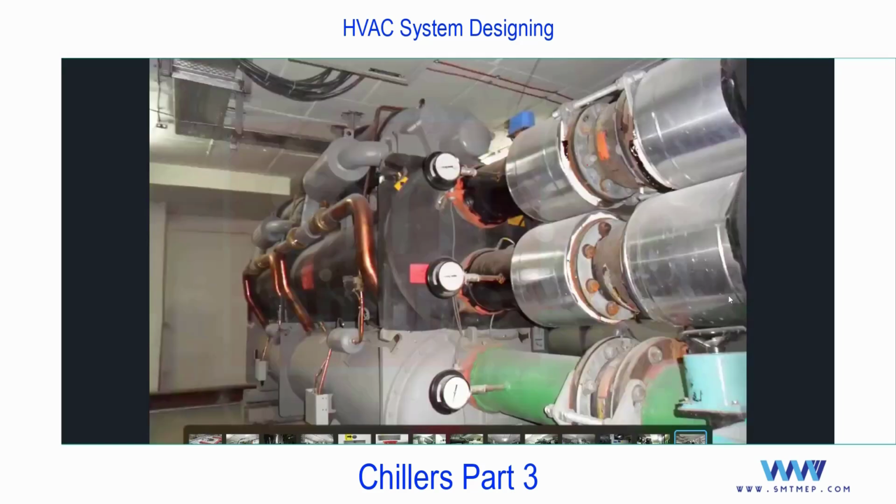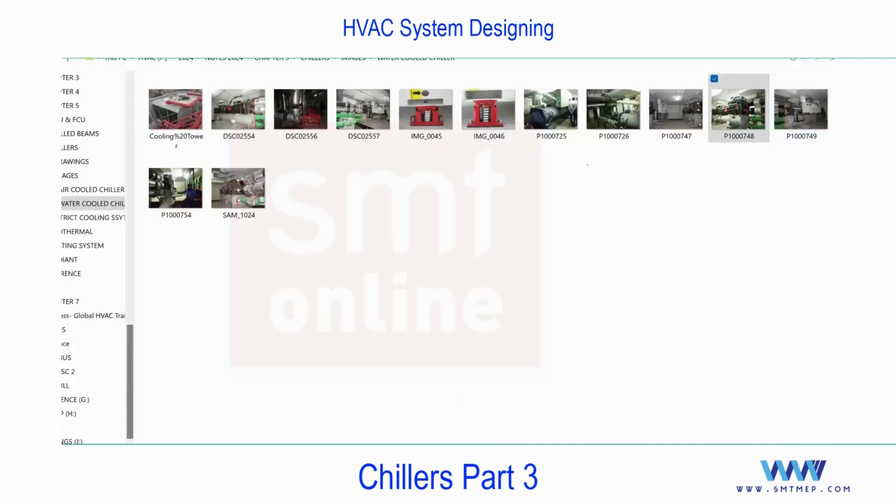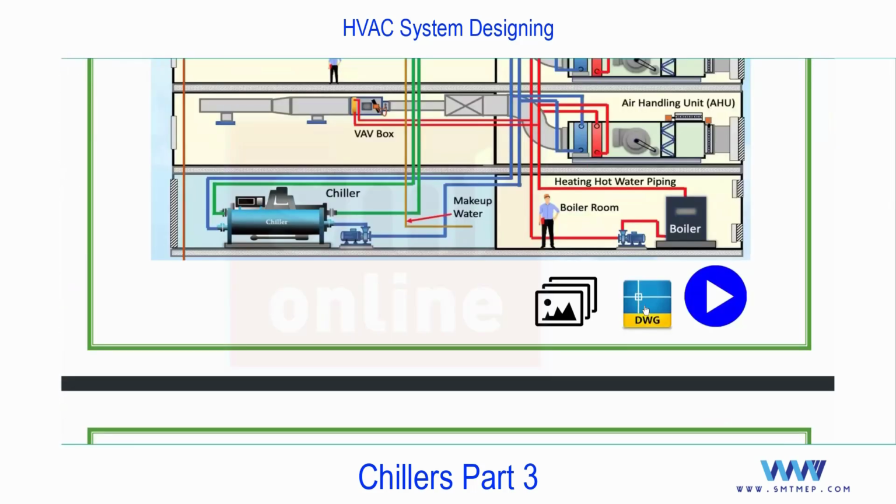This is very, very important from an interview point of view and for installation as well as for designing point of view. Designing point of view for pump selection, because all these accessories and the fittings will create a higher pressure drop. So that must be considered at the time of pump selection. So as a design engineer or as an installation engineer, for both, these accessories are important. So we have a separate detailed topic in part 5. So at this level, we're just learning how this system works. Okay, so let me proceed. We'll try to understand with the drawing.